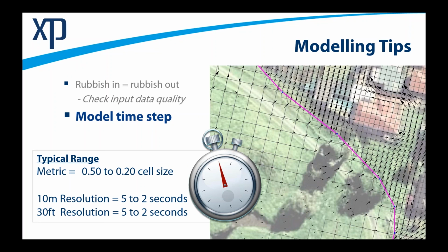Number one, your model will take longer to run. Number two, often it can actually hide issues with your topography data that would otherwise send a model unstable. So if you work within those bounds, that's usually the recommended approach. So you don't want to capture water every centimetre running down a 1 metre plane. You really just want to capture it there. You don't need to go the whole way.